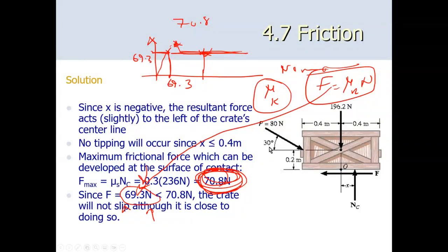Okay, Barnaby, you just joined us now. Let me tell you what you missed. Here, friction force, you are familiar with friction force. There are three zones: no motion or onset of motion when the static friction formula applies, and the kinetic friction, that is when the object is moving. But the difference here, how is this different from your previous understanding? In this subject, Barnaby, we are talking about the rigid object. We are not talking about a particle.